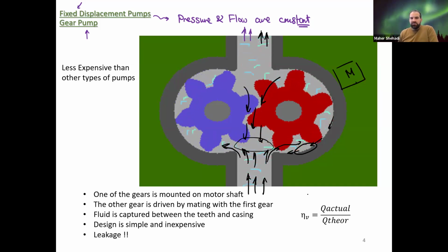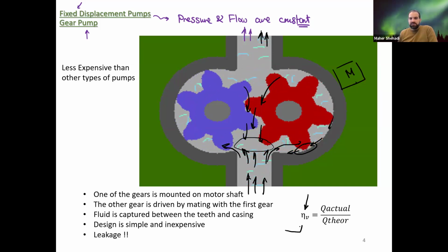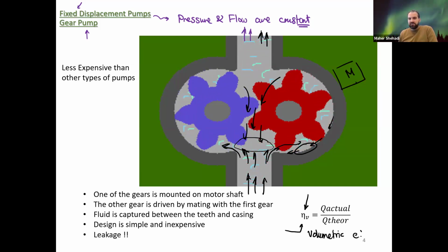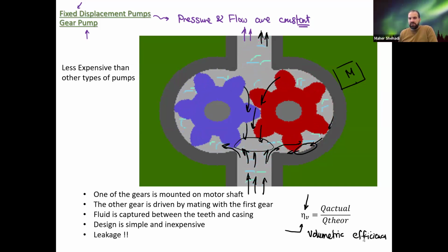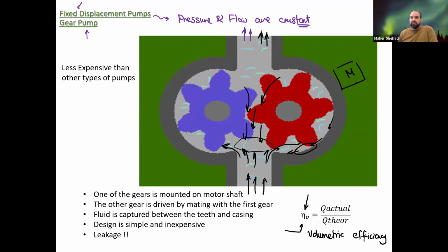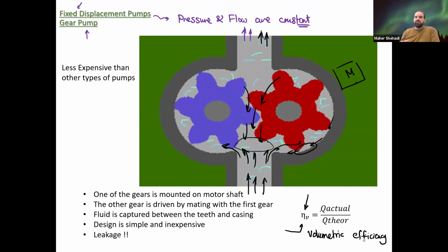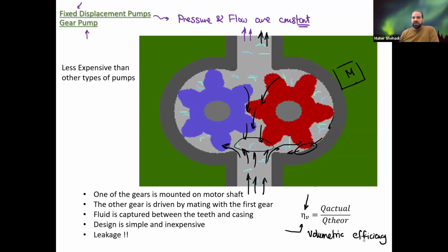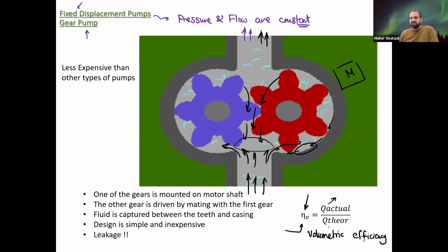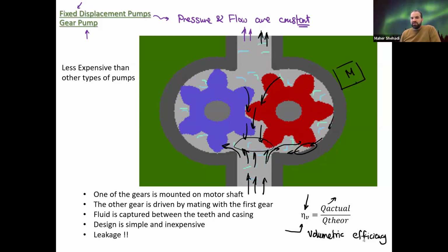Okay, so this is the first efficiency. If you recall, we're reviewing those. So that's called the volumetric efficiency. And it's equal, if Q is the volumetric flow rate, so that's the actual, when we say pump, we're delivering flow. For motors, we take flow in. So for pumps, how much I'm actually delivering. So that's the actual flow rate divided by the theoretical, the design value that we calculated or we designed this pump.